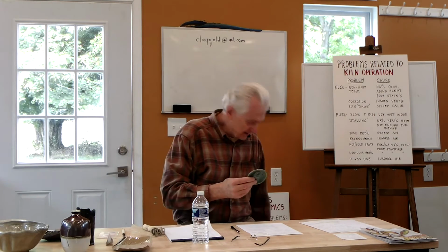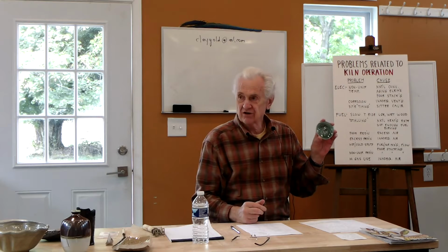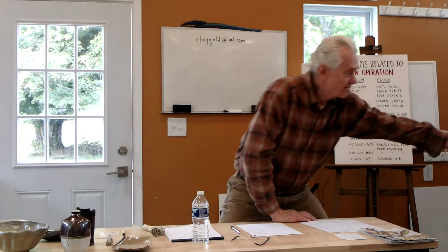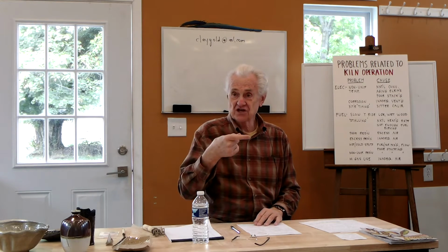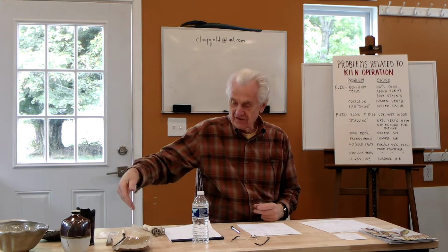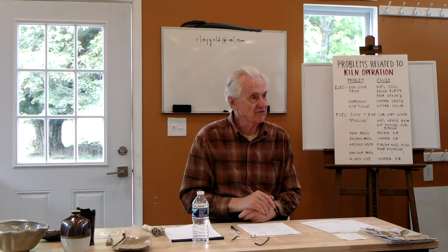This is an example of a little dish that was sitting on a shelf underneath the thermocouple. When the thermocouple corroded, chunks of the oxide landed on the pot. They fell down because the thermocouple was hanging over the shelf. These are little bits of the metal that fell off the thermocouple. Some big pieces fell, and they landed right on the glaze and ruined the pot.